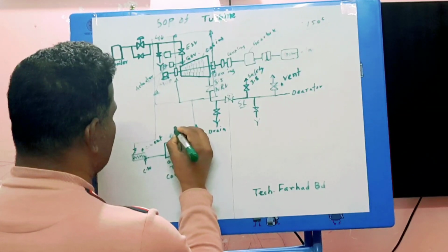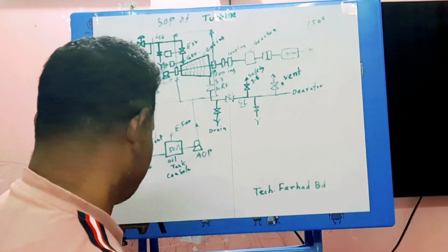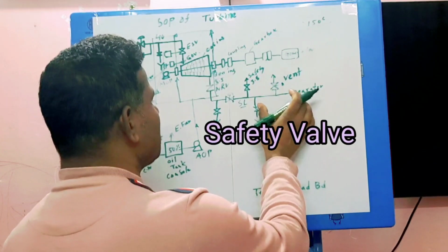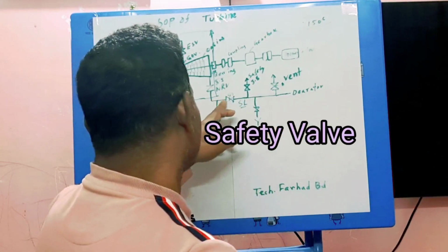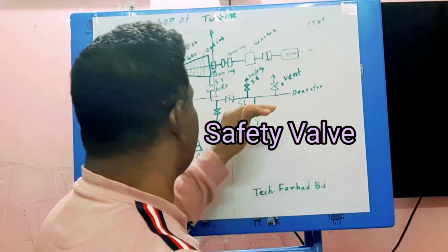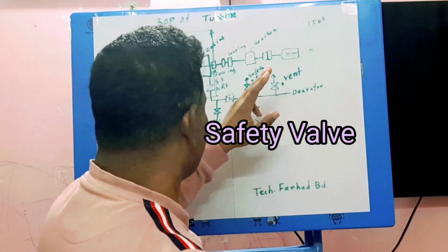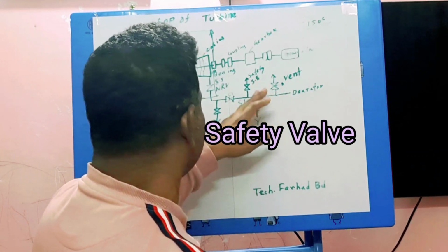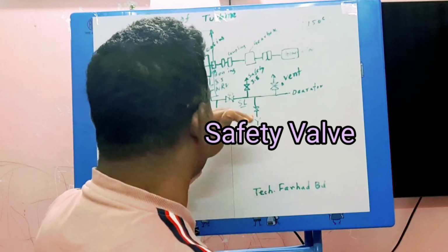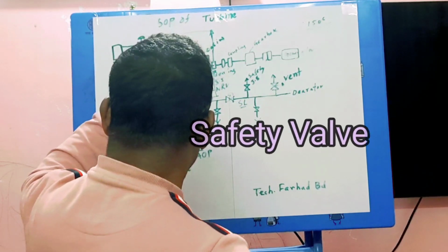Exhaust fan for reducing the oil temperature. Safety valves are used for controlling the SL steam pressure. If any equipment trips, it is possible for the SL line pressure to increase. If the SL line pressure increases and it is not possible to control this pressure, it is possible to trip this turbine.